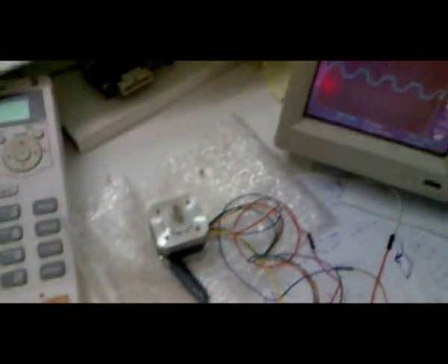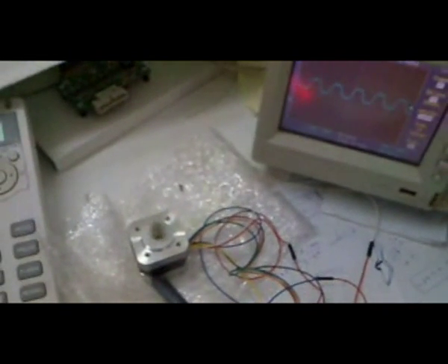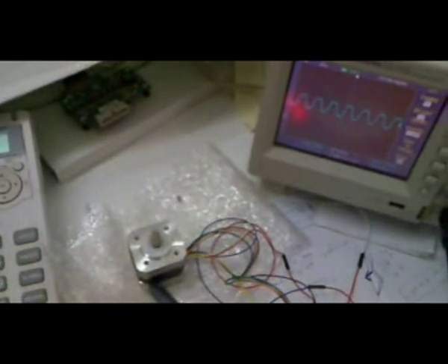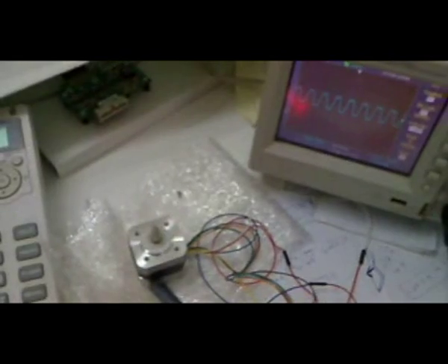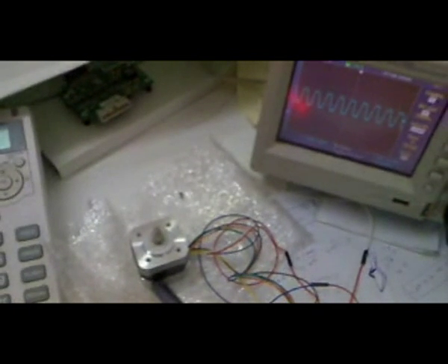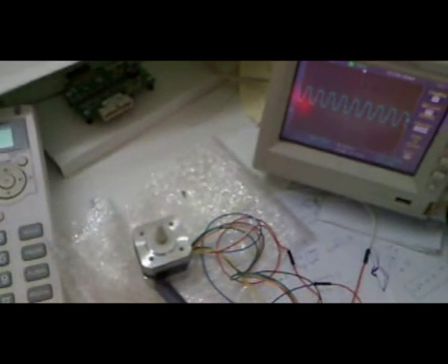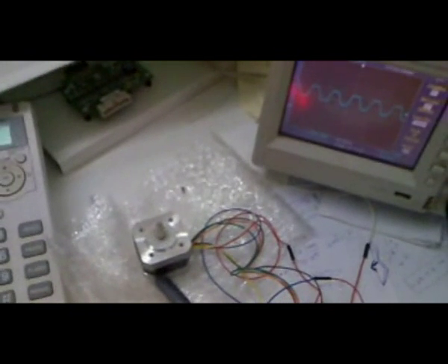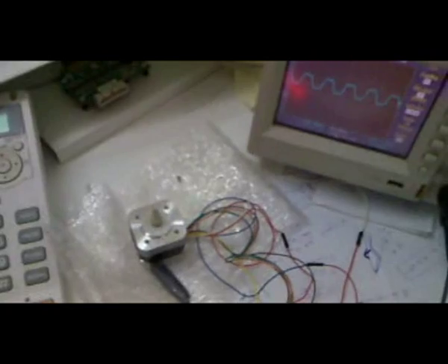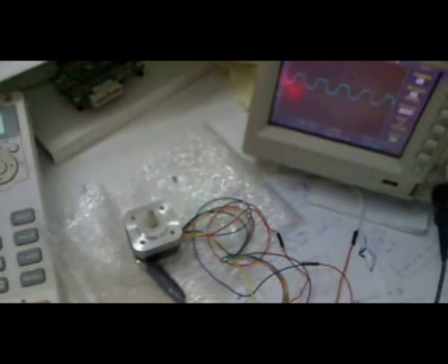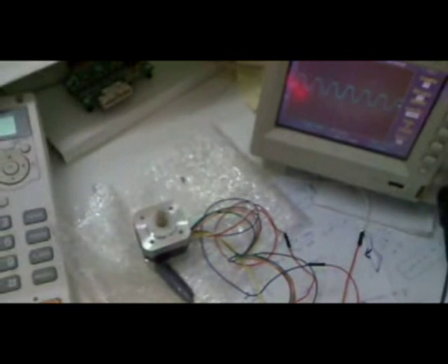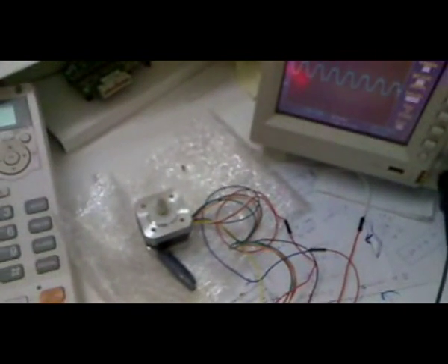For more lively info of what is going on, the PWM duty cycle of one of the phases is tapped out and displayed in the oscilloscope. You can notice how the frequency of the waveform, and thus the speed of the motor, varies with the potentiometer input, which I am changing. The frequency of the waveform is the electrical frequency of the motor, which is nothing but the rate at which the stator coils are commutated. The speed of the motor is 1/4 of that frequency because of the presence of 4 pole pairs in the motor being driven.